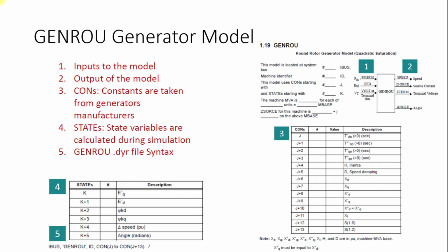When you go into this version, there is another folder with the name of docs. When you go into this docs, you will find a file known as model.pdf, or there is going to be a folder with the name of model library, and inside this folder there is going to be a file known as model.pdf. When you open this file, you have all the models which are available in PSSE, which can be used to model different control features of different electrical equipment.